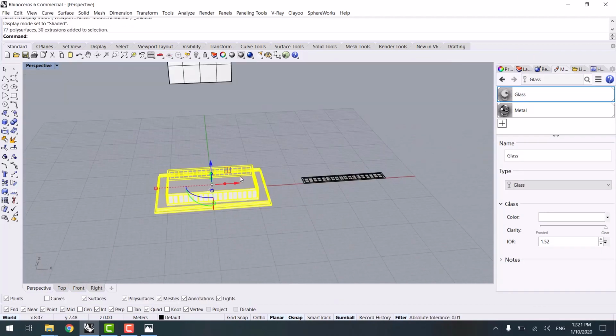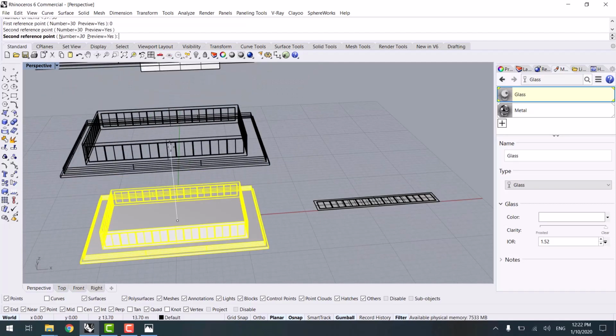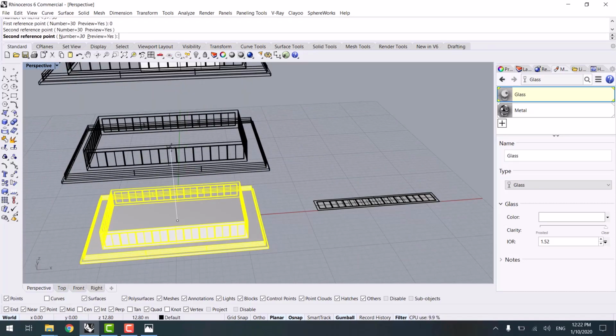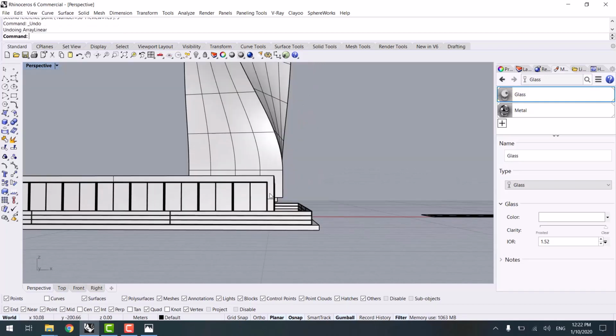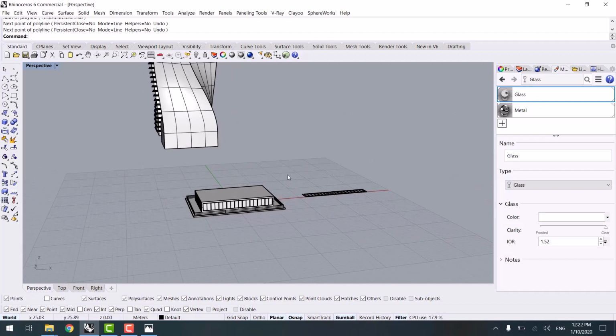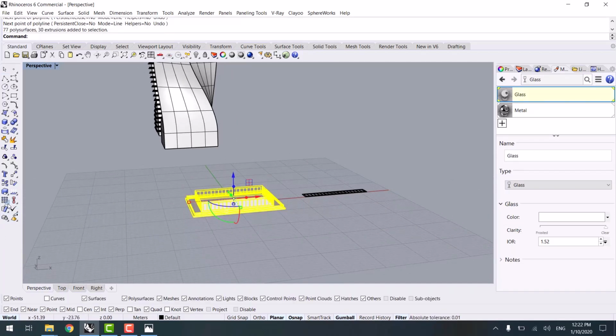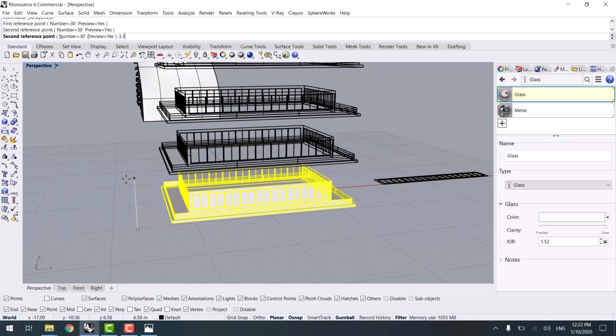Now what we should do here is that I select this, I activate array linear. Now I want 30 floors from 0 center. I hold control and I go up as much as 3 meters, I think. Much as 3 meters and 30 centimeters. Yes, that's right. The number is correct. Again, I activate array linear. 30 floors, and here I give it the number.